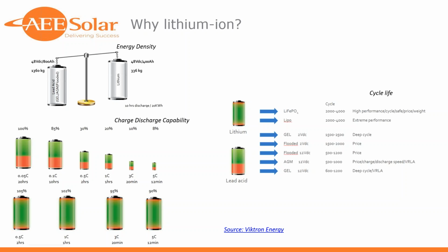And I think this is where there's been the most water cooler talk or chatter around lithium ion: cycle life. The way that AGMs and lead and flooded batteries are rated is, they'll give you an amp hour and they'll give you a cycle life. Lithium ion's a little bit different in how those are typically warranted and rated, but very, very good cycle life performance.